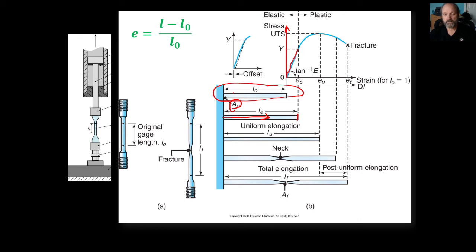That's called the elastic region, where it's kind of straight, and it has an angle to it. It has a slope to it. If I keep pulling, then the material is going to start behaving a little bit differently. Start stressing it out, and it starts to bend over. Now my force is less, but I'm still making it longer. That's because it's starting to get thinner and it's easier to pull apart. And then you get to a point where snap, it just breaks. That's what they're showing in this part of the graphic.